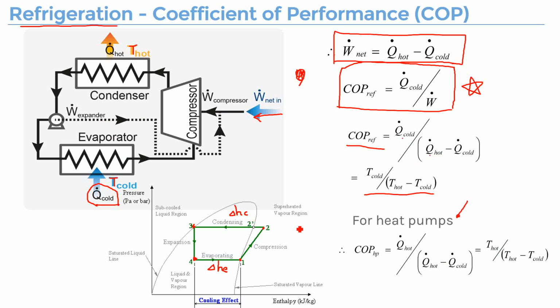Okay, so if we stay on this one, this COP value, I'm not sure for the products here, but I know for all the products back in China, they must label these COP values on all these air conditioners. So of course, for COP value, the higher, the better, because that means you provide higher cooling power. But now here I have a question. What if you find a product where the COP value is low, or in operations you find out the COP value is really low? Where could it possibly go wrong, or what would be the issues for this system?